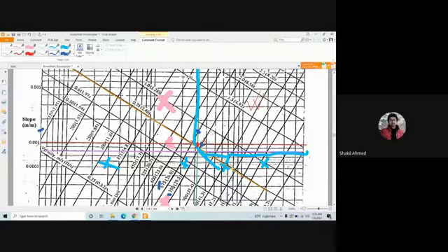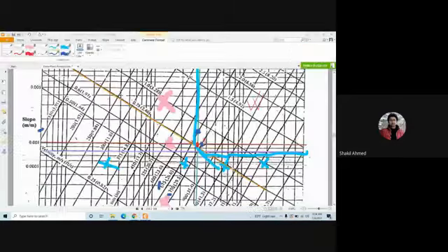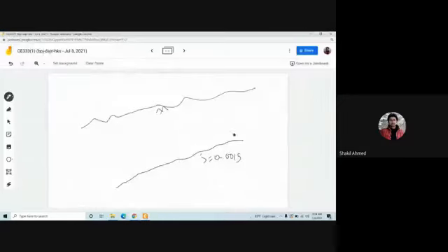Now, on a net basis, as a combined whole, which one is going to be cheaper? You need to do both of them. First, you take this diameter and this slope, and you calculate how much earthwork excavation you need. For example, this is the ground, and your sewer is going to be laid in this direction. S equals 0.0015, for example, in our case, for this point.